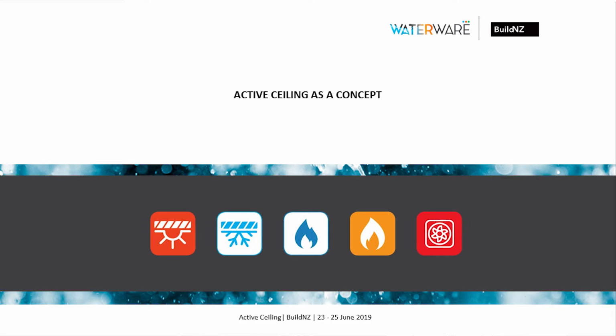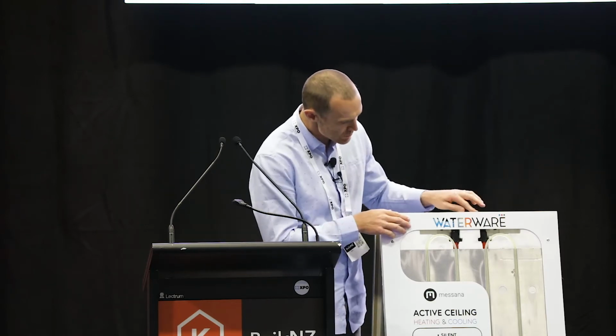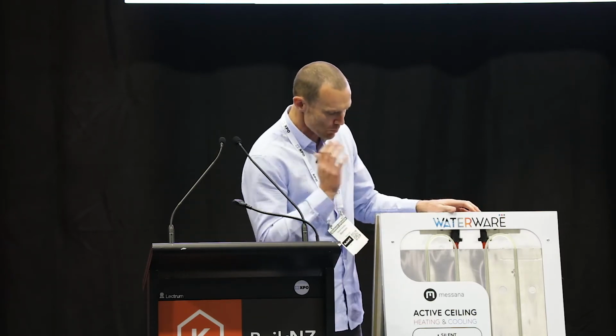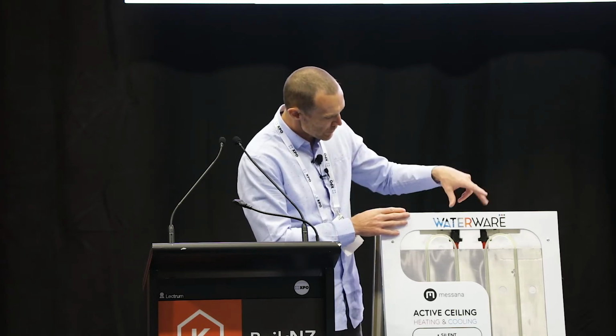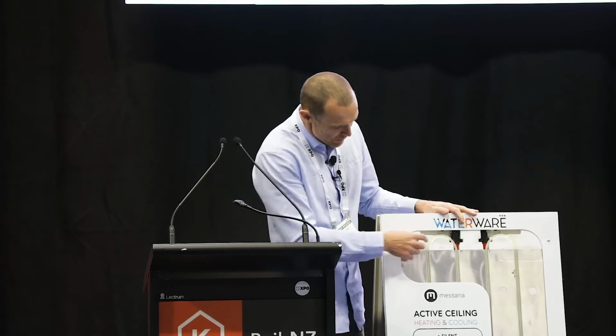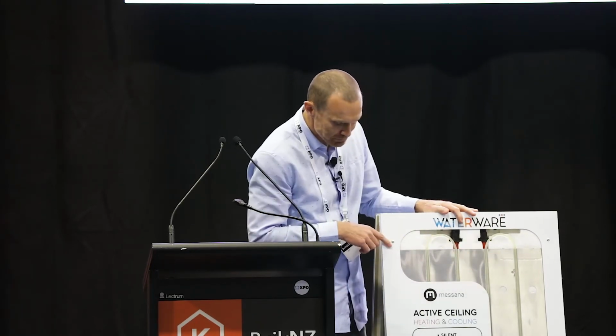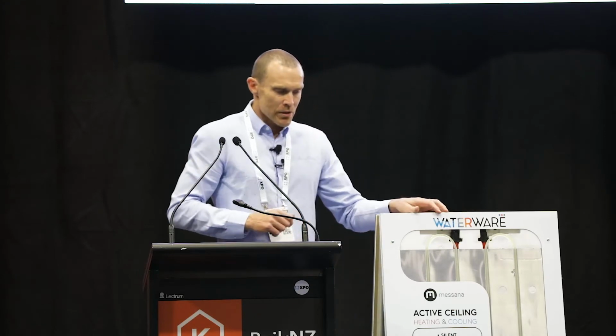Okay, so more specifically about active sealing. This is an example of a panel here. So this is designed to go behind the jib, and then you put a normal jib over the top. You have your 2 pipe connections here for your water in and your water out, and then your heat emitter is basically in these smaller pipes here.